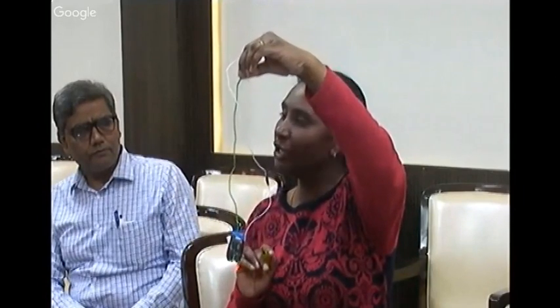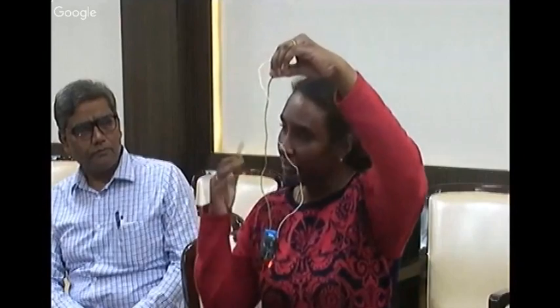You need to know that when you want to turn it off, you require commutation. How will you do it? Remove the supply. So with DC, no problem. Supply is not there, it automatically turns off. Or if it is AC, or even in DC, when you want to forcefully do it, you can give a reverse voltage. Like if you have a capacitor or inductor, reverse voltage across this can also be given. So if I remove this cathode, automatically this will get turned off.